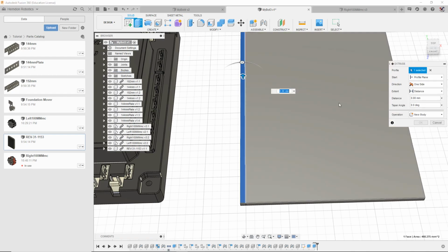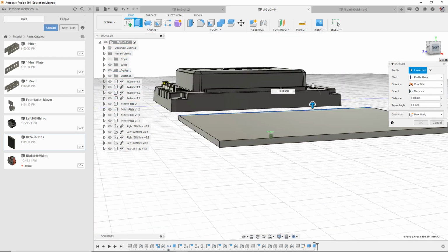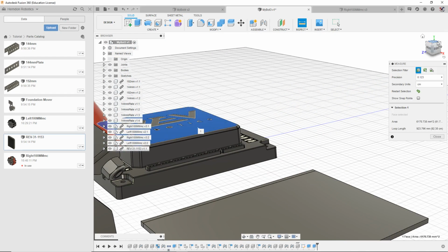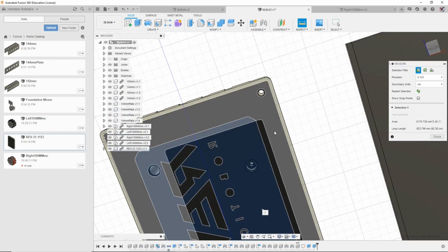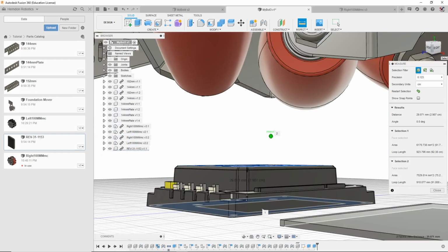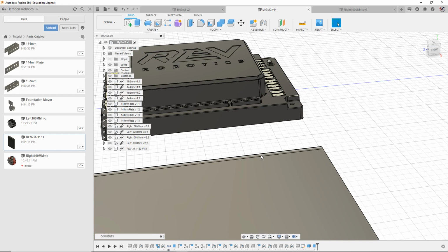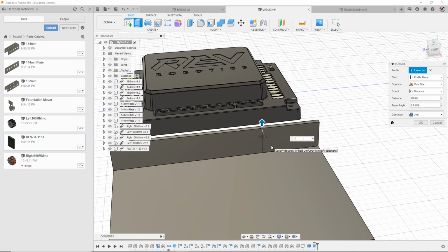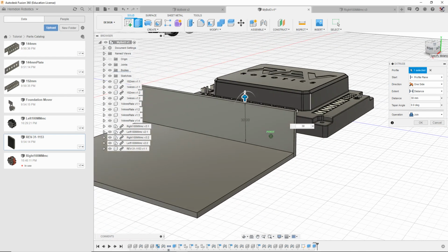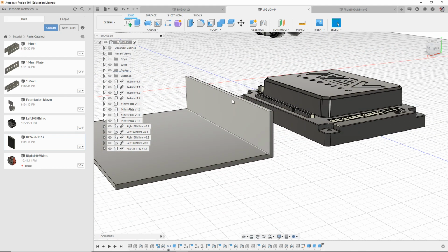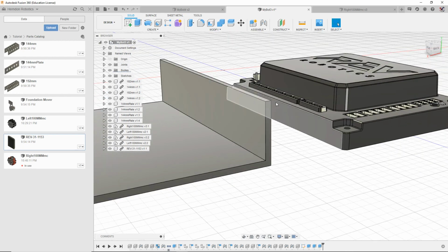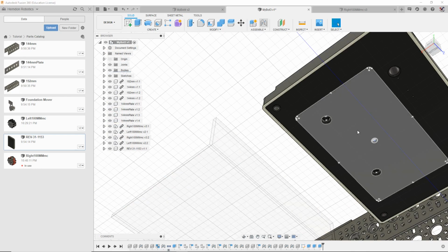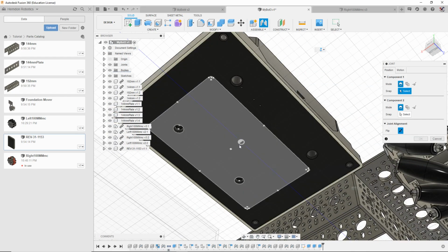So come here, extrude this up by about, let's actually measure this. So I can come here and get this face, then measure this face, and it's about 30 millimeters. So we'll make it a little under 30, so we're gonna make this 30, and then this join will work like that, and then it will automatically connect it there, making it nice and smooth. So now all we have to do is joint, come here, select the middle.